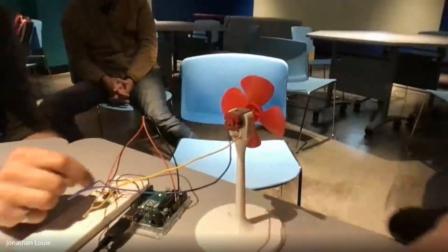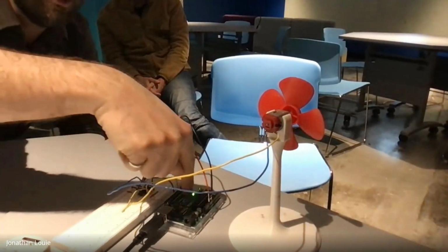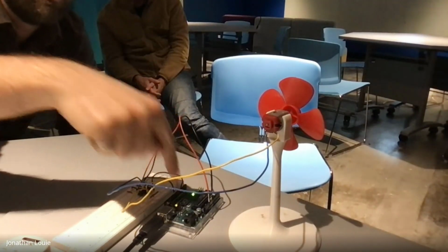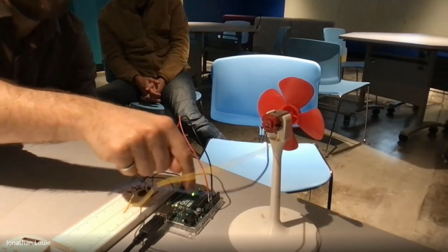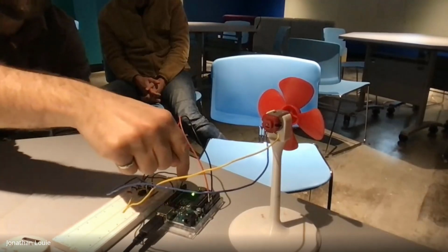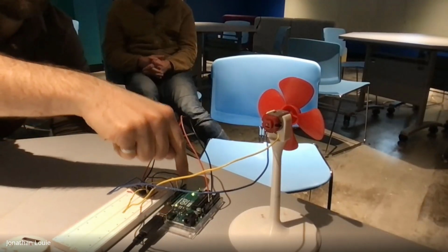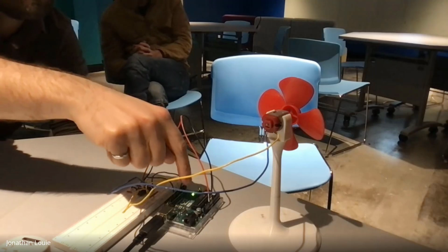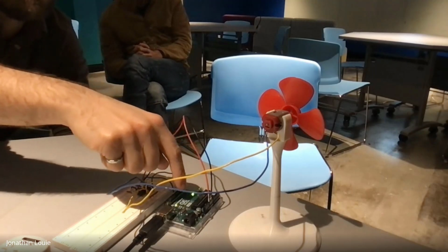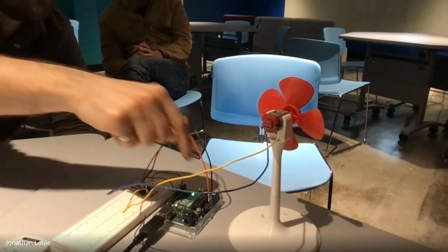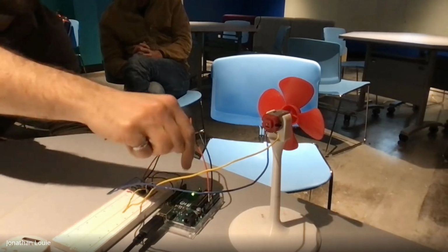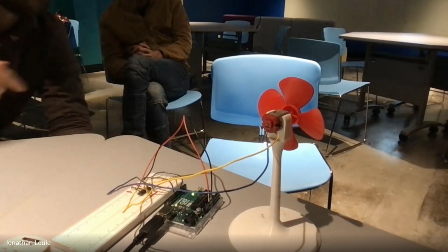So if my motor, I should point the camera at this stuff too. Yeah, so if my motor driver were instead, say here, it looks like there's kind of an empty spot. If that were here, then it would actually be soldered into this board. And instead of the GPIO pins going to the vertical pieces that I've got the wire sticking into, there would just be a small wire inside this board that goes directly from the microcontroller to this thing. So it would just be directly connected. Oh, it wouldn't have to go through wires like this.